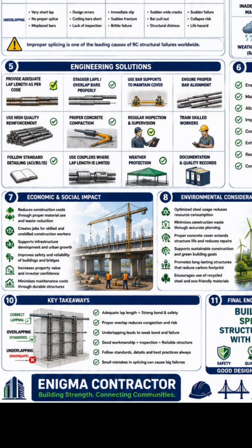Then proper concrete compaction. Yeah, when you are doing concreting, it is also important for you to ensure that you do proper concrete compaction. So this compaction is done to help your concrete fill all the voids, so that you can get the best concreting. Then we have regular inspection and supervision. So it is very, very imperative for you to do the right checks, do the proper inspection and also supervise all those ascribed to you to supervise.